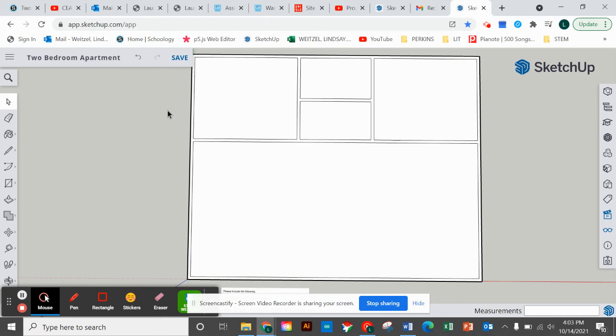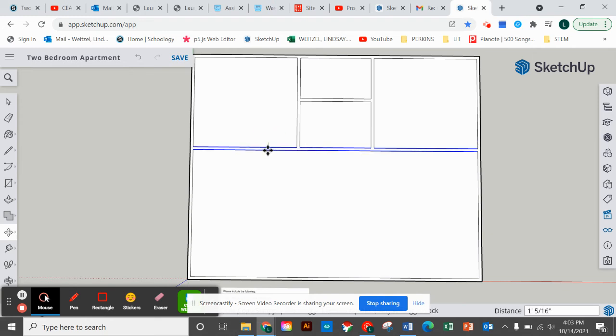So what I'm going to do is I'm going to start here on the left. I'm going to drag a box across that includes that middle wall inside of it. And I let go, and it only gets the middle wall because that's the only thing that's completely enclosed in that box. I'm going to tap M, my move tool, grab that edge, and it's going to grab both pieces. So I click one time and start dragging down on the green axis, and I type 1 foot 6 inches. And just like that, we have moved it down 1.5 feet,